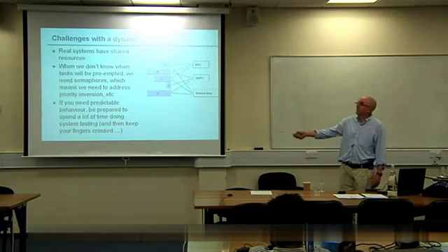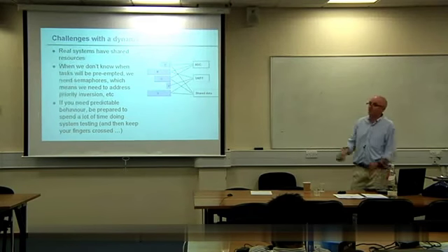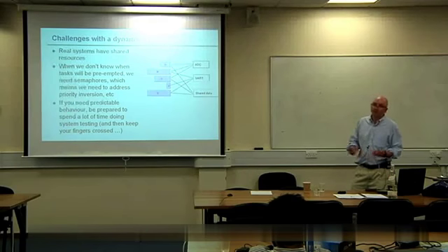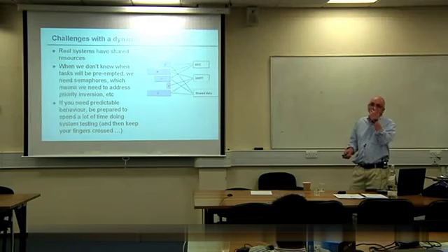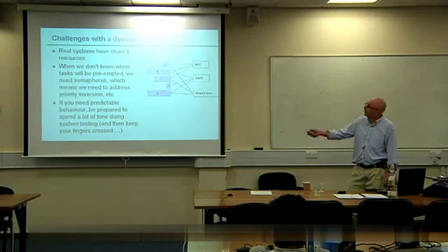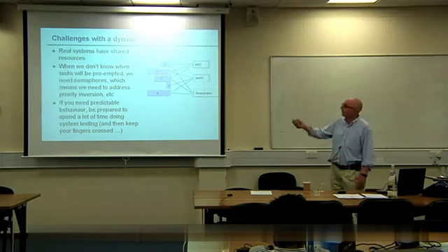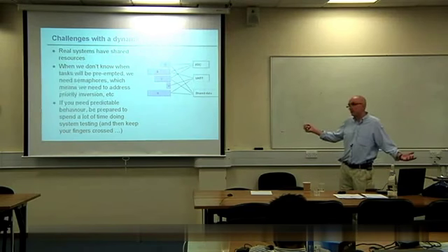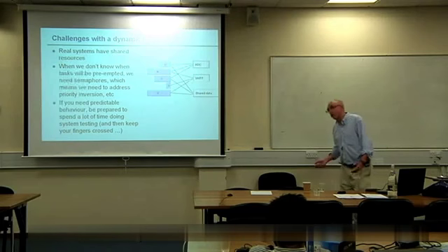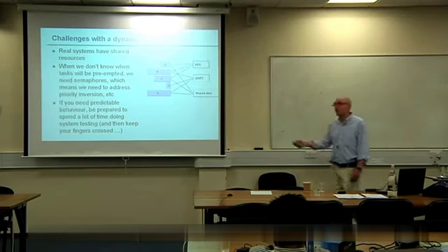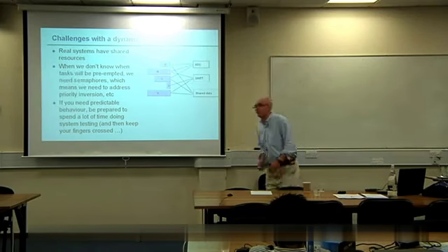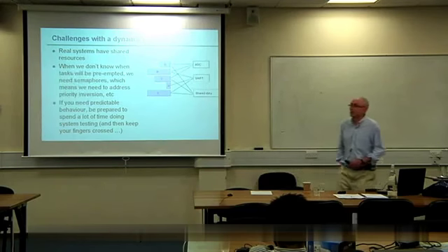If your system uses about 20% of the CPU resources, you've got a small number of interrupts, typically around 20 tasks or less in your system, you can probably make this work in an event-triggered design. If you have something of greater than about 20 tasks on average, as a rule of thumb, it becomes a practical impossibility in most systems to ever iron out the possible combinations of conflicts and constraints you have here.